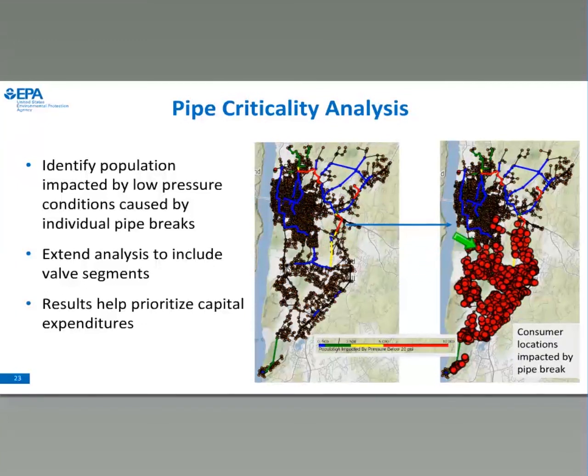So this is valuable information for the utility, that maybe they would like to say, hey, we need to have backup supplies to help make sure that if that pipe were to break, we would be able to get back online immediately. And for this analysis, we did different pipe break durations, like we looked at pipes broken for 48 hours versus 96 and saw the differences there.